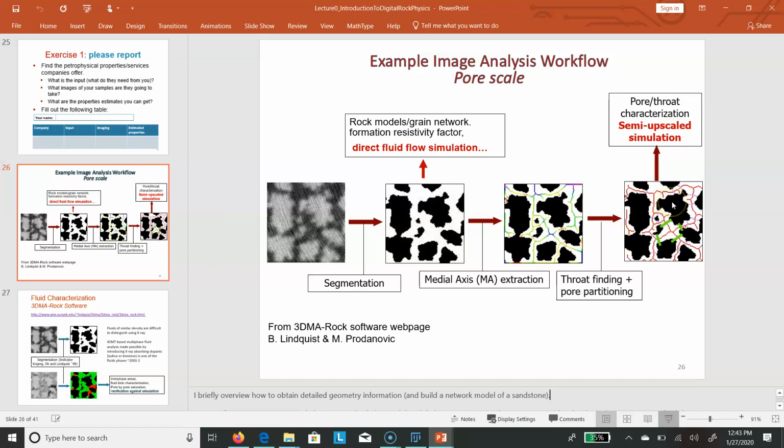And they happen to be identified by software. This is how I spent half of my graduate school, looking for these in a sense. So essentially, this is a pore throat. And now I can organize this pore, this pore, this pore, this pore. They're linked through, and I can organize them in a so-called pore throat network, that I can then use simplified formulas on.